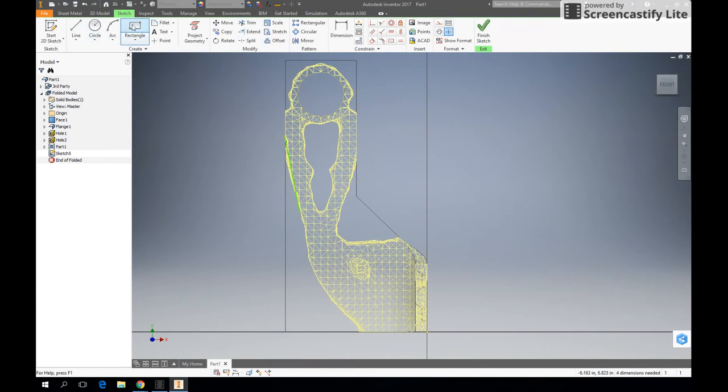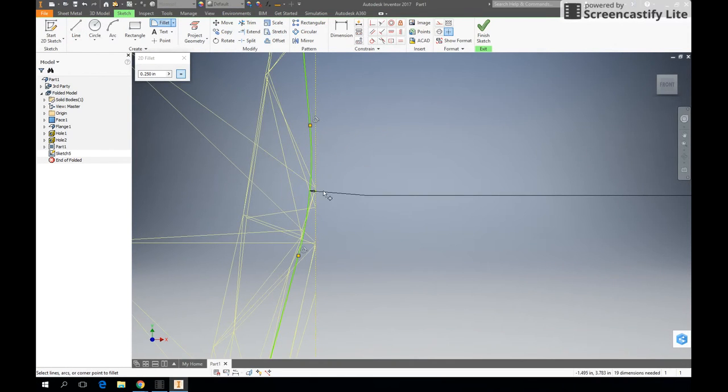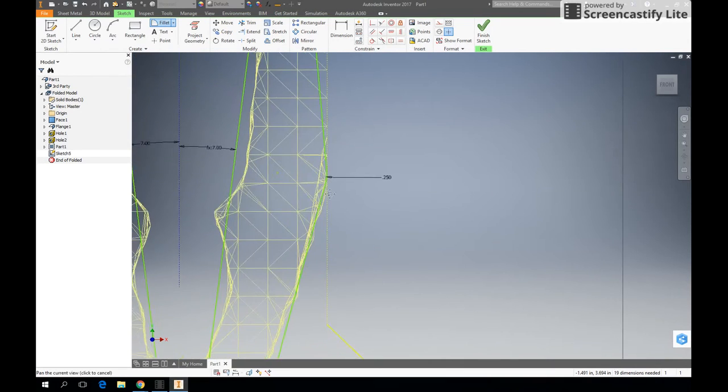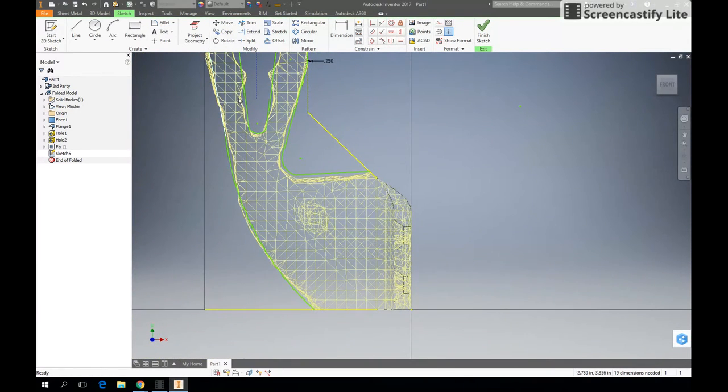Tracing the suggested part is required so a cut extrude can be used to get the part into what Inventor suggests. As you've seen, the shape generator promoted a shape that you may not have expected. This shape comes from finding the low von Mises stress points in the part and cutting out the amount of material to reach the specified weight reduction, in this case 40%.